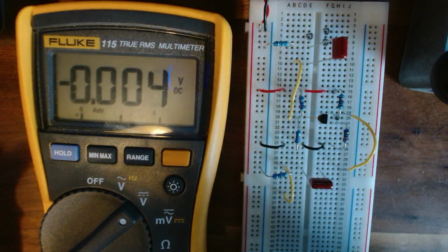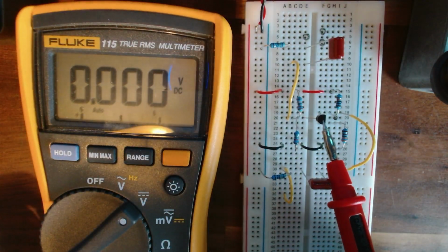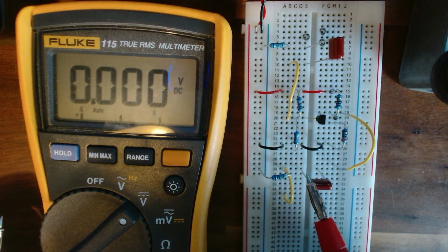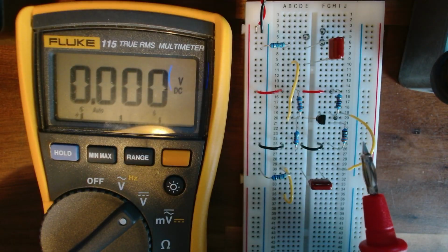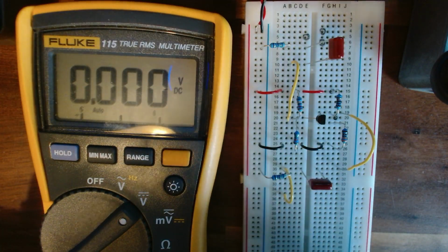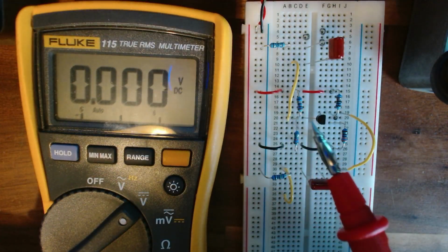We can adjust our numbers. There's things like this chip might not be exactly 200 HFE. These resistors might be a little bit off. And we'll see this when I come back to our measured numbers a bit later on. But it's always good to do this once you've worked out where you should be.